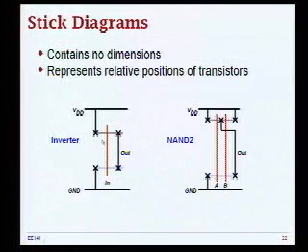So this is a common strategy that we've already seen earlier in the class, that people use in constructing standard cells and layout in general. It's sometimes useful just to figure out the relative positions of all these objects in layout, and then use this simplified stick diagram type of representation, and then just throw this in the tool that has all these algorithms that we are going to explain under the hood, and you eventually get automatically generated standard cells.